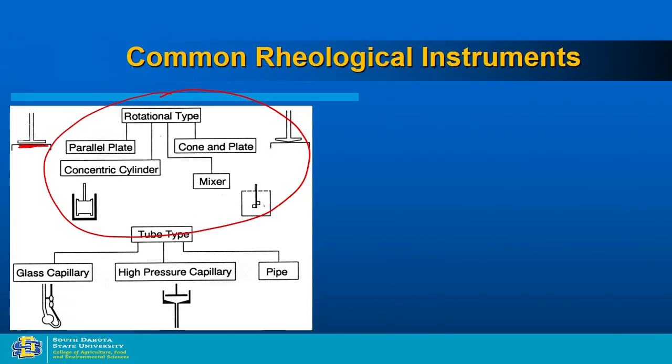The rheometer, you can use it, for example, this instrument. This is not an instrument, these are the different configurations. The rheometer is the instrument which can be used for solid material, semi-solid material, and liquid material also. So the same rheometer, you can use it to measure the viscosity of fluids. You can use it to measure the viscoelastic properties of solid and semi-solid material.